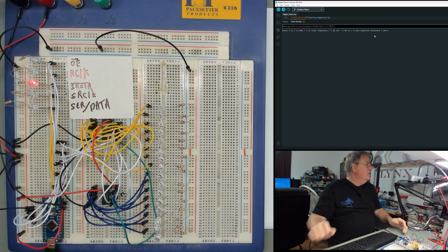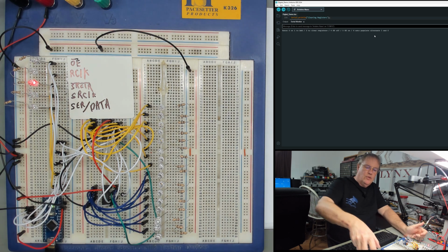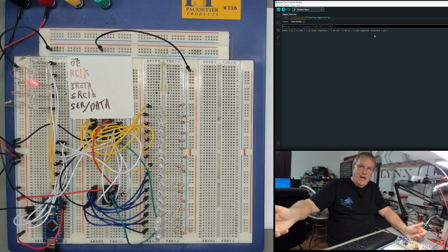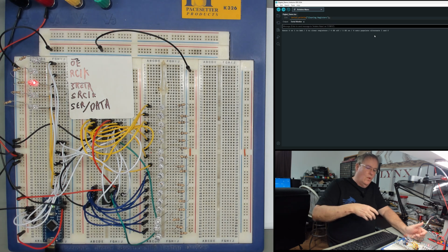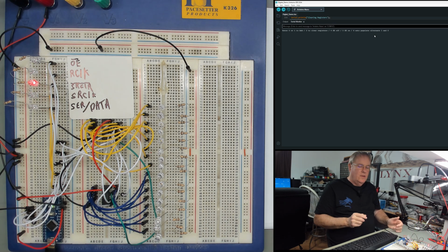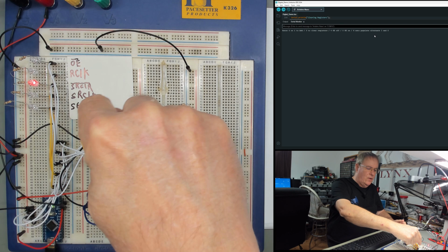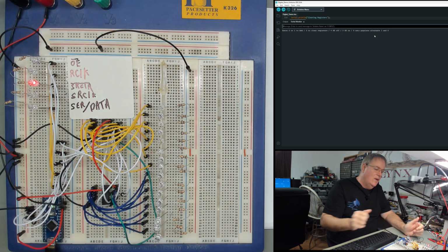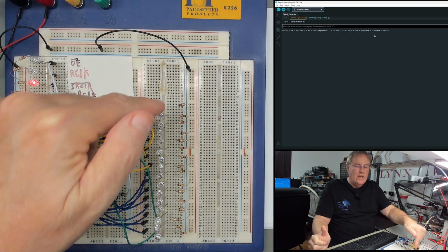If you remember your chip design, you've got your shift registers in one column and you've got your storage output registers over here that actually turn the ports on or off. What we're going to do right now is tell the system to clock a 1. Everything is clear. Clock a 1 into the shift registers, which would be the first channel up here. It then will clock it from the shift register out to the output, and since we have the output enable on, you'll see it actually come on.